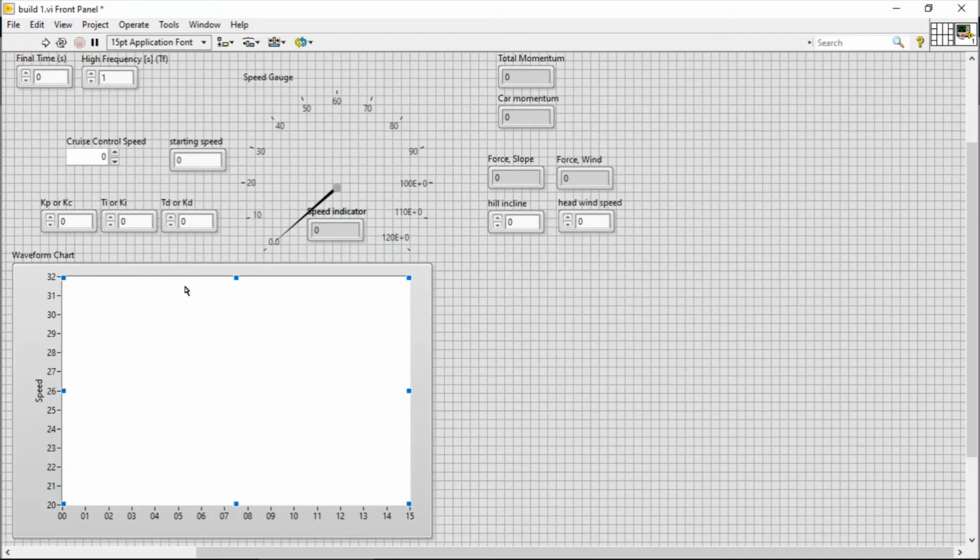So the second one was to maintain less than 1 meter per second squared of acceleration. This is well below the limits of gravity because, like I said, we would have to get to 9.8 meters per second squared to exceed that, and that's when the tires would actually start losing grip on the road. So I just wanted to avoid that a little bit.